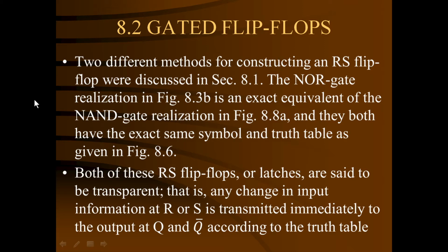To prepare this kind of clock RS flip-flop, two additional AND gates are connected at the inputs R and S, and one input of both the AND gates is shorted, and a clock input, or enable input, is connected.